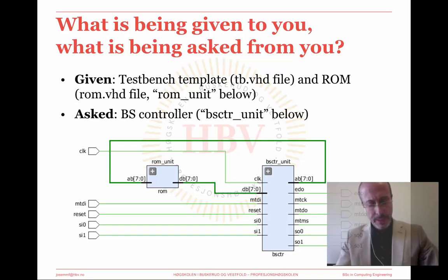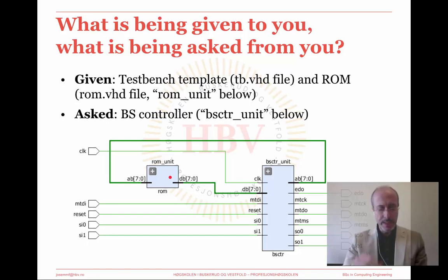So, what are you being given and what are you being asked? You are given a ROM description in a file called ROM_unit, or in a file called rom.vhd, which contains the test program to be executed. This ROM has an 8-bit data bus and an 8-bit address bus, and it has no control signals, so there are no read or enable signals.